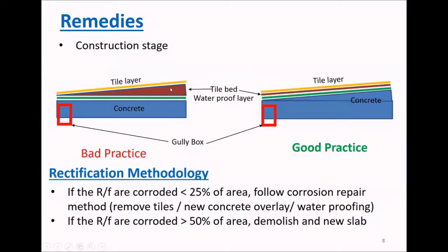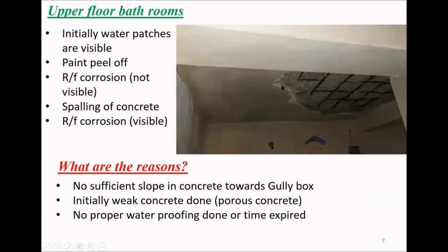Remedies, as before: we have to remove this old concrete surface, the mortar bed, totally, and we have to make this concrete slope, right? Then only we can apply our waterproofing. These are the remedies and rectification. Now there's actually this kind of corrosion.